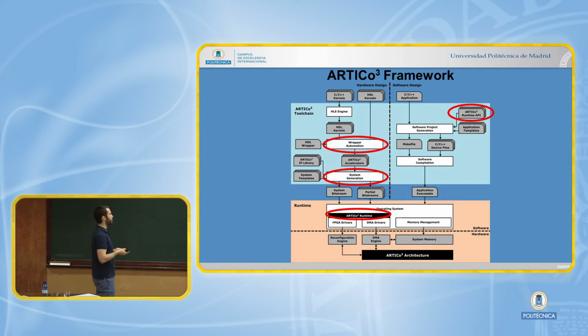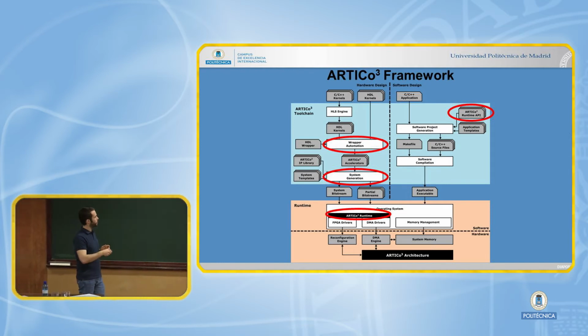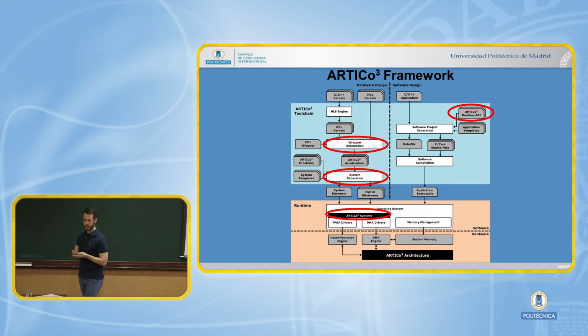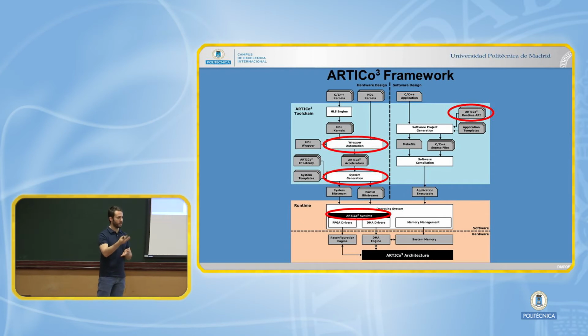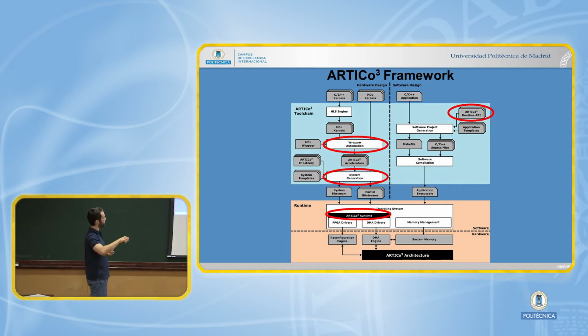And basically, the proposal of this thesis is a framework that you can barely see. At the top, it provides a toolchain that provides a way to describe your application in C, C++, and then generate both the executable that is going to be running in software and the dedicated hardware accelerators that are going to be changed in the FPGA. This is the hardware flow, and this is the software one.